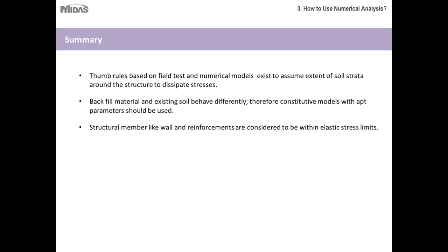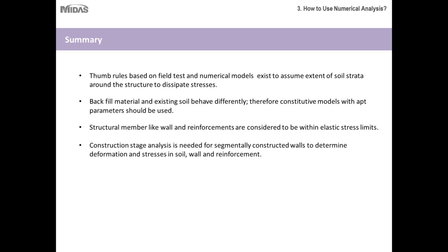Then backfill material and existing soil behave differently. Therefore, constitutive models with apt parameters should be used. The structural members like the wall with its foundation and reinforcement are considered to be within their elastic stress limits.